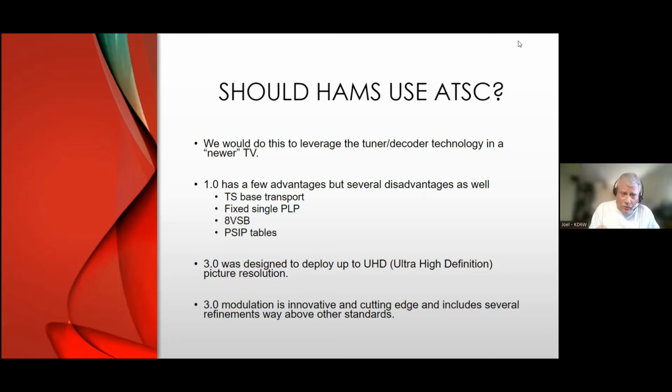But 1.0 by itself means a new modulation, compression, transport stream, all this technology. So it's more than just 8VSB. It also includes PSIP tables, and has this fixed PLP as a base transport. All these things added together create what's called ATSC 1.0. For example, 3.0 had a similar concept when they came up with the standards. There are like 16 base documents that, when you put them all together, allow you to broadcast 3.0, but they come in different parts and pieces.